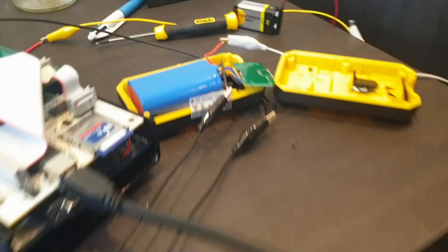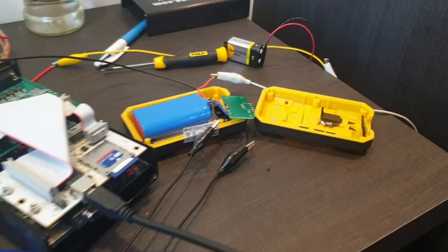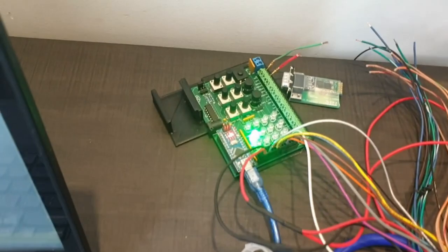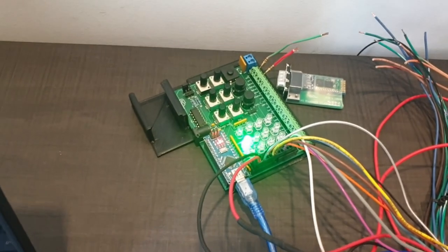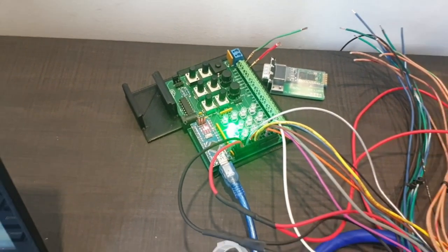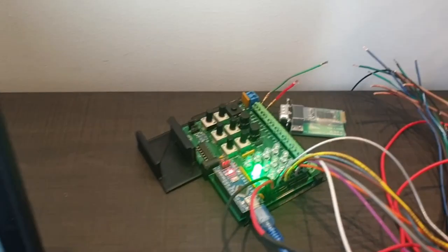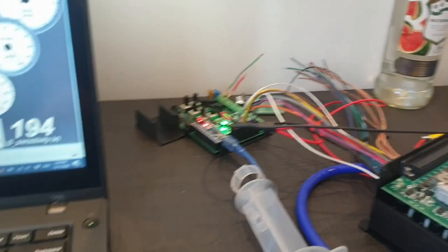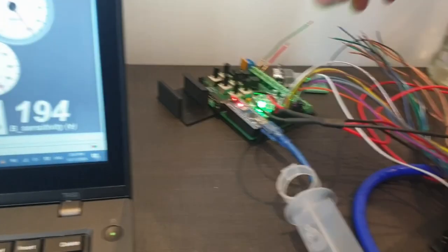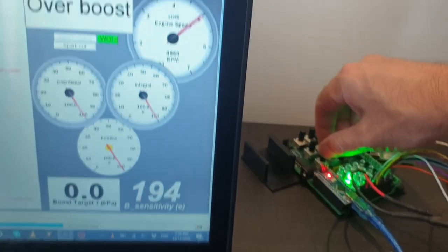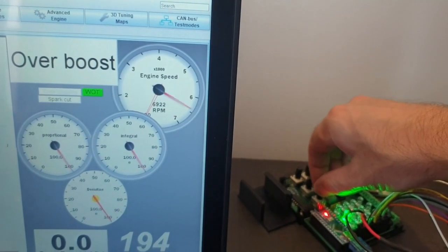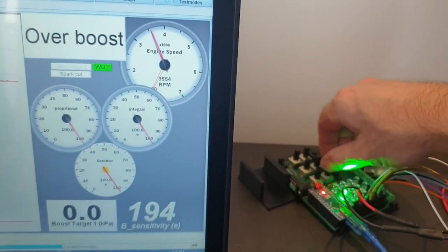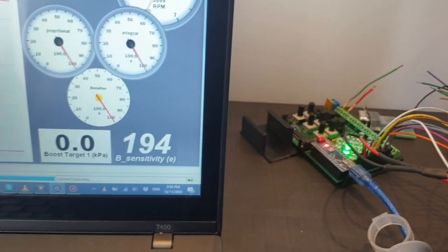We're running off a couple of different batteries because that's what I've scrounged up in my hotel room in quarantine here. We're making the whole shebang work with the RPM and TPS through this. It's an engine stimulator I built myself. Basically it uses the RG-Stim software, and all I need really for this testing is some pots that control engine speed, and one that does TPS, so that'll get us through the tables there.